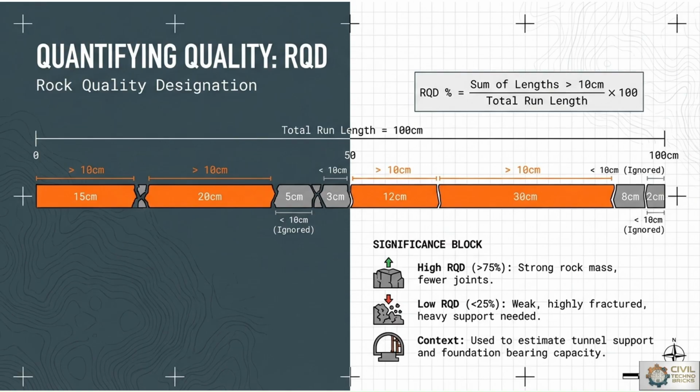The electrical resistivity method is also used to check the resistivity of the ground or below the soil layers and rock layers. Different geological materials show different resistivity values, so those resistivity values are also very useful for rock quality designation and its nomenclature findings.